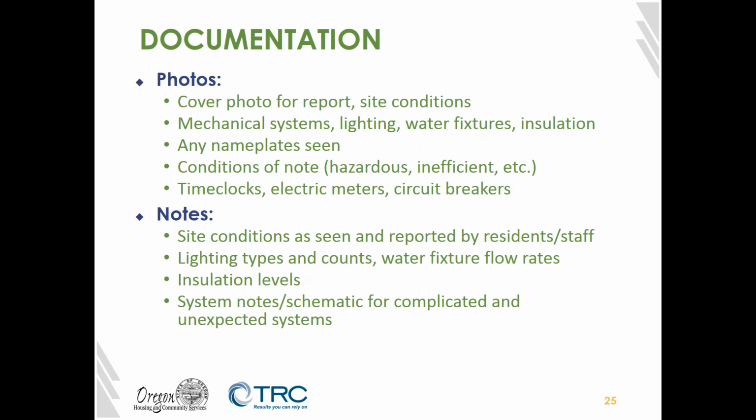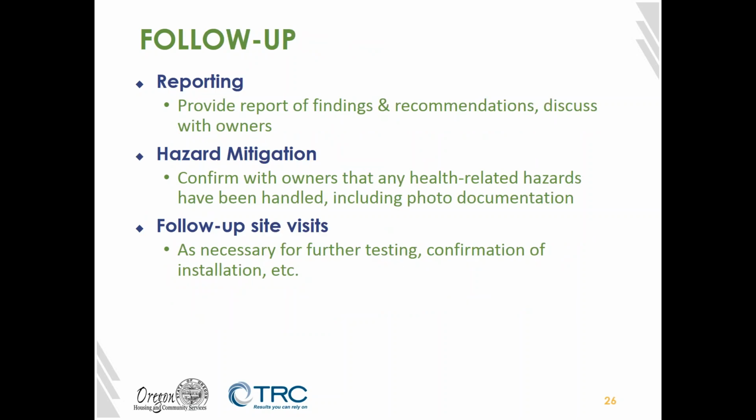This just helps us keep track of what's there, but also to give a good report back to the owner after the fact, where we can actually include pictures of what we're referring to so that you can see what these systems are. Anything that we can't take pictures of, we'll be writing down. So writing down the thickness of the insulation or notes that the staff gives us about what's going on, the counts for the lighting, how many of each light fixture we see, that type of thing.